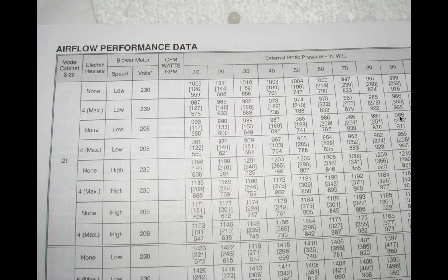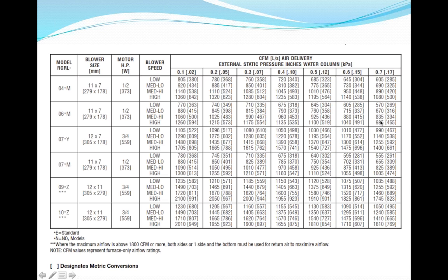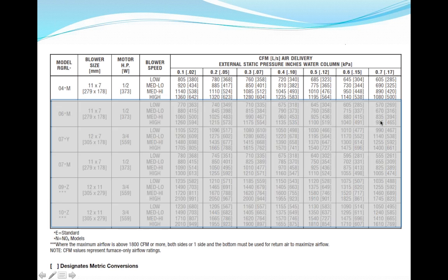So that's where you have to be careful with an ECM. If it's undergoing too high static pressure outside of its range, it could be consuming gobs and gobs of excess electrical energy. Let's move through that and take a look at another chart.